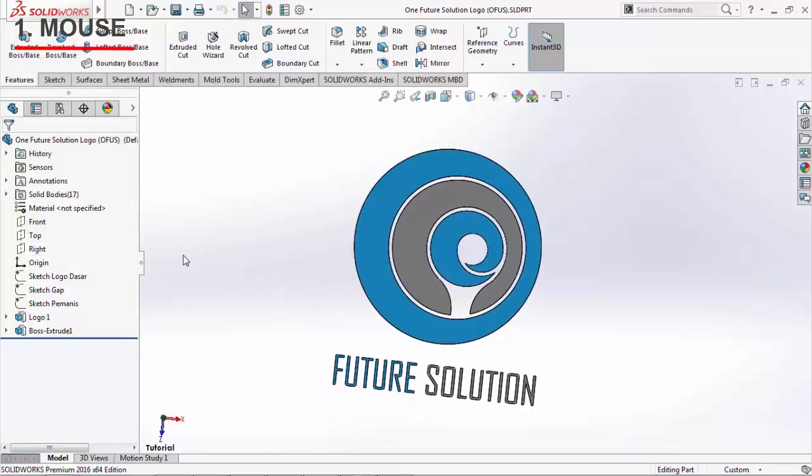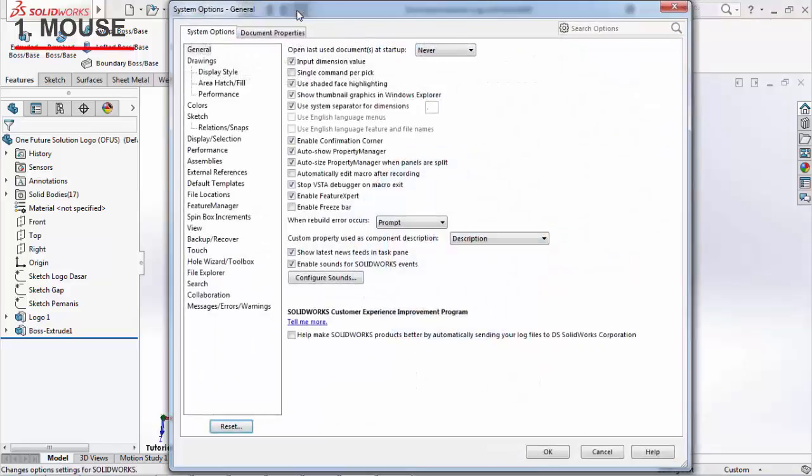After we learn how to use the mouse and its functions, there's the last lesson about the mouse: how to reverse the mouse direction when scrolling up or down. We can go to the options icon in the standard toolbar area, then click the icon. Make sure we are on the System Options tab. Choose and click View.